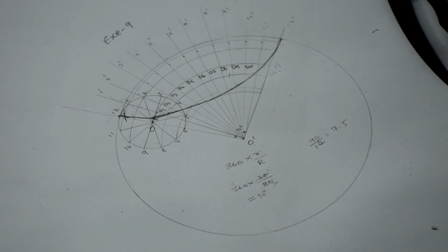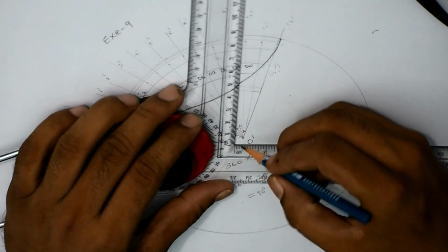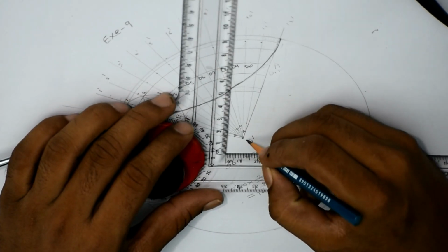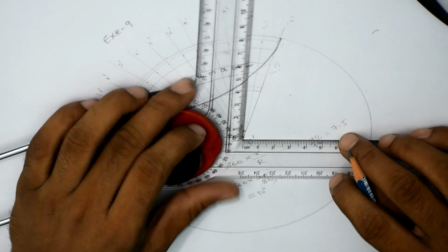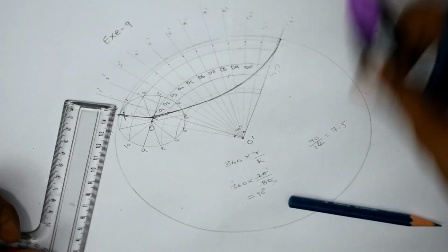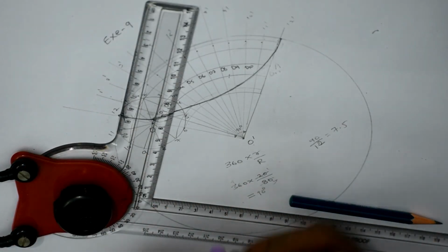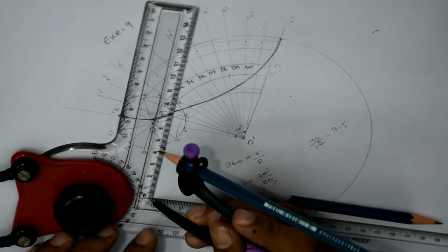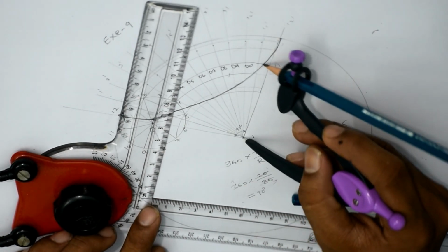we have to take that tangent and normal also at a distance of 60 mm from the directing center of the directing circle. So this is the directing circle and the center of this circle. I need to adjust this scale, or else what I can do is measure the distance 60 with the compass, and I will cut one arc here.